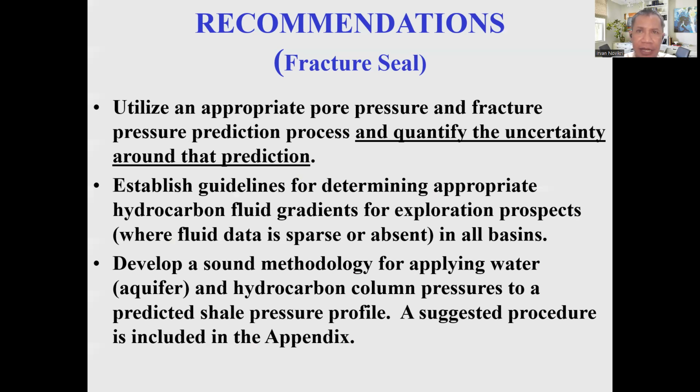It is suggested to establish guidelines for determining a suitable hydrocarbon fluid gradient, particularly in basins where there is limited or even no available fluid data. This guideline would help in predicting the appropriate pressure profile for shale formation, incorporating information about water, aquifer, and hydrocarbon column pressure.